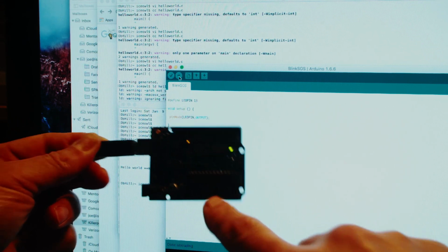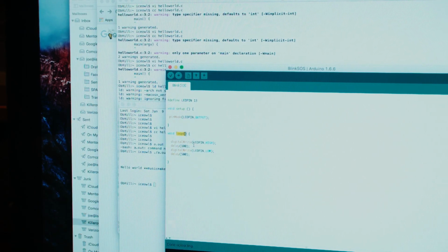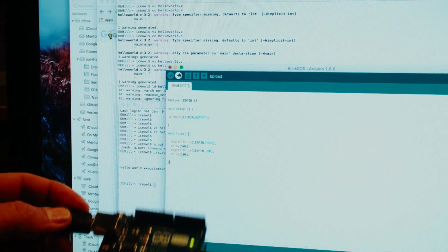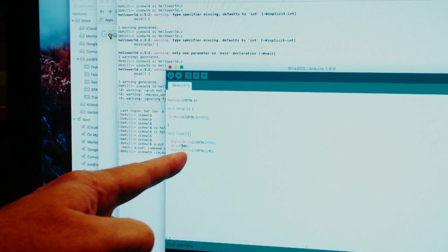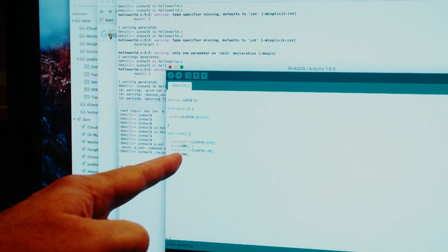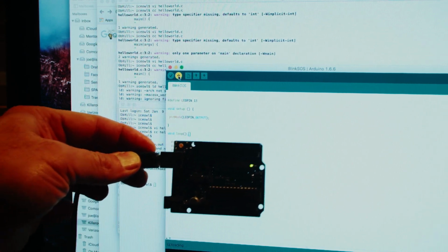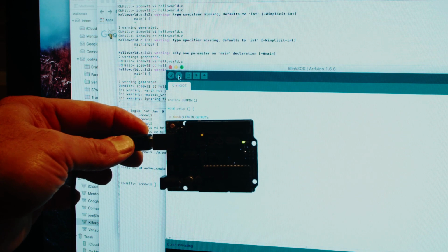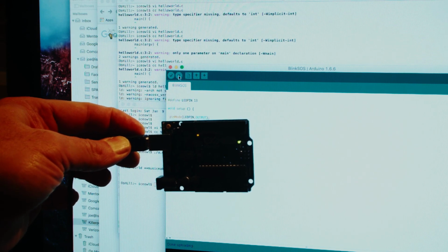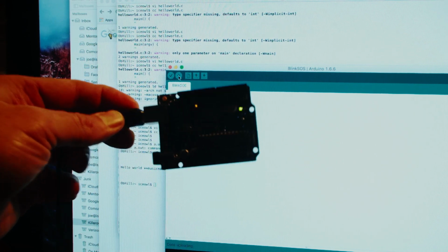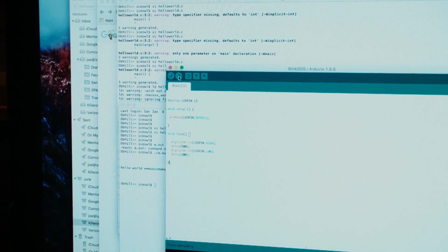And just to show you that we're not lying here, I'll do the opposite. I'll turn it on for half a second and off for 1/10 of a second, just by simply changing those variables. So turn it on, wait half a second, turn it off, wait 1/10 of a second. Let's shove that in there. And now you see it's mostly on. Okay, so that's how easily that worked. Now let's try this with one of the other Arduinos.